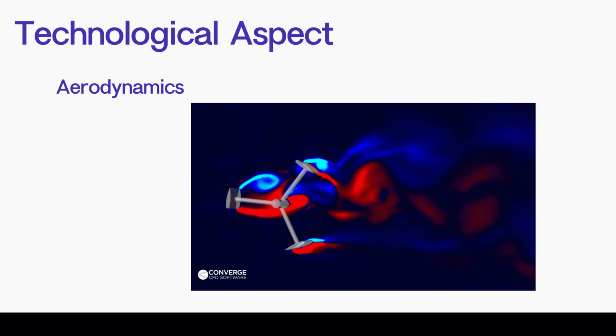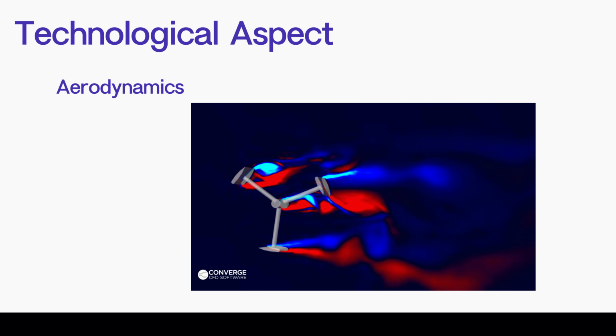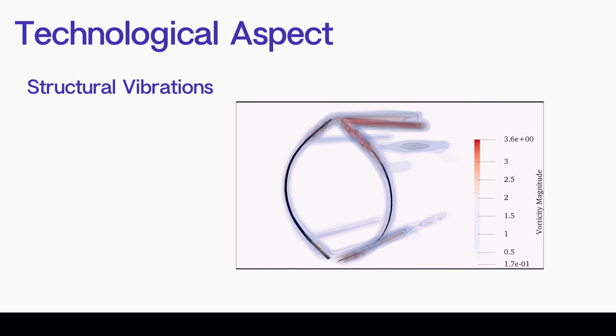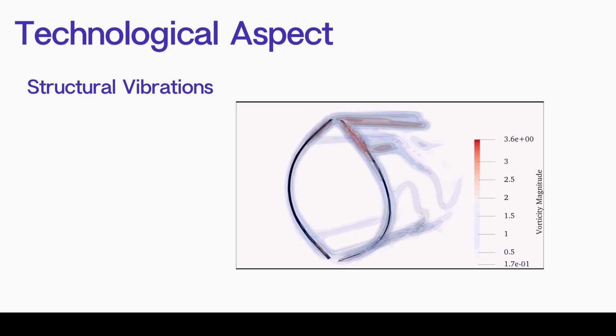Although Darrieus rotors demonstrate good efficiency, vibrations and resonances pose complications, necessitating additional precautions and limiting the use of higher masts, particularly in small wind turbines at many inland locations. In the realm of vertical wind turbine technology, wind tracking plays a crucial role in accessing strong winds.